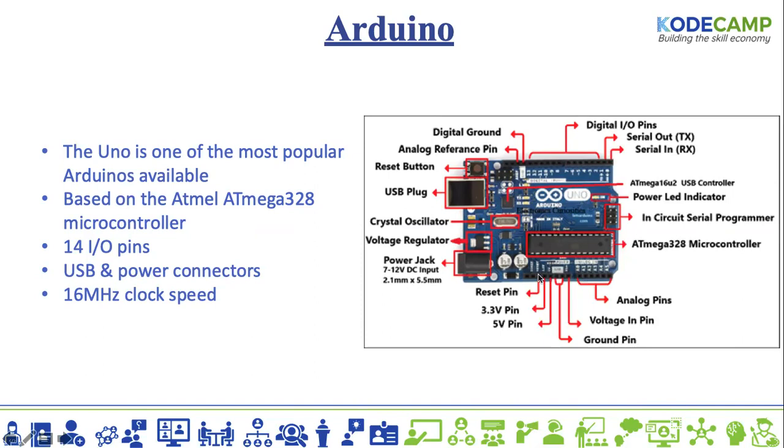you can also do a kind of electronic reset. Maybe you just want to reset it electronically. Yeah, you can work with this particular pin to reset it electronically. So this is the reset button, and this reset button is connected to this. The only way to use it is to pull the data to ground. Just have a pull down resistor and put the data to ground, and then it will reset this particular Arduino.